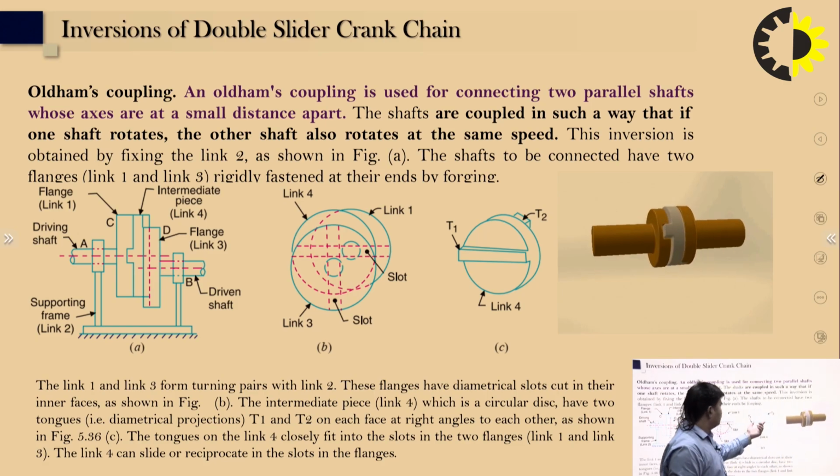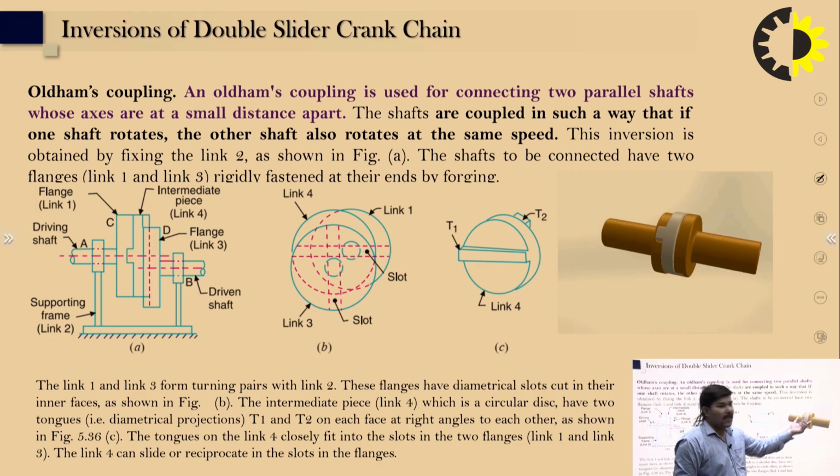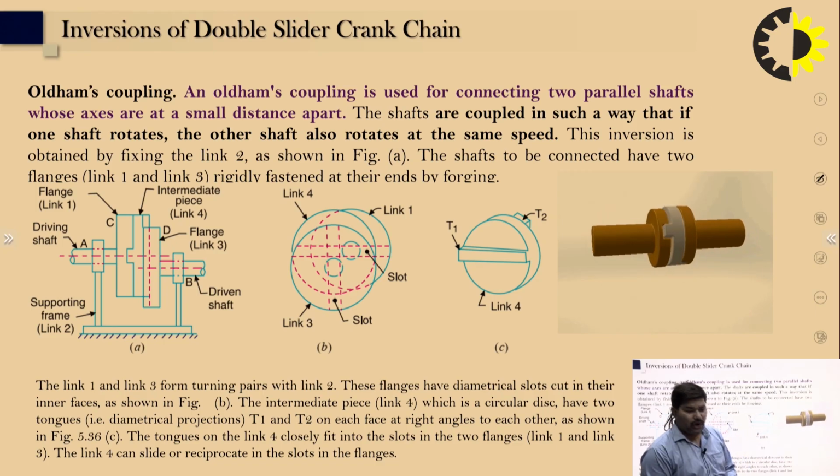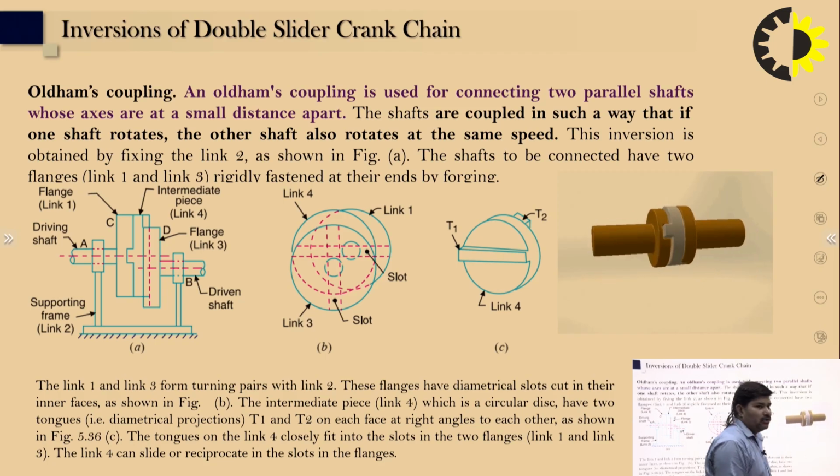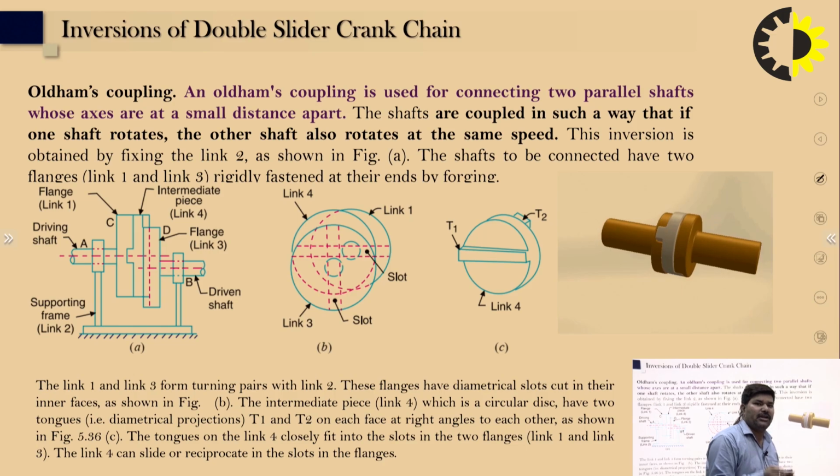So the Oldham coupling connects two parallel shafts rotating in the same direction, and it uses this inversion of the double slider crank mechanism.